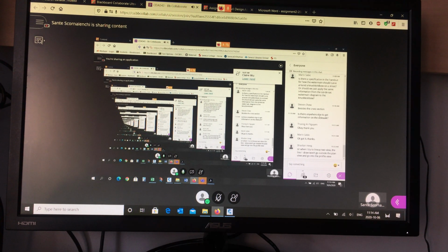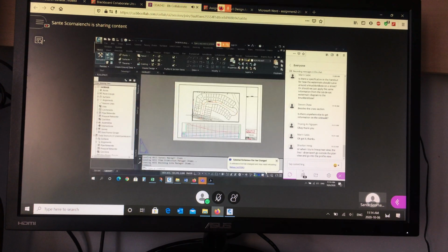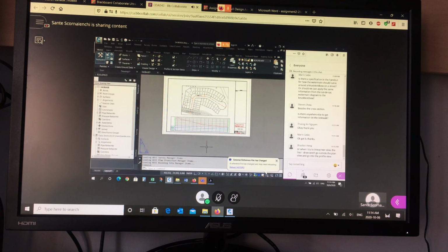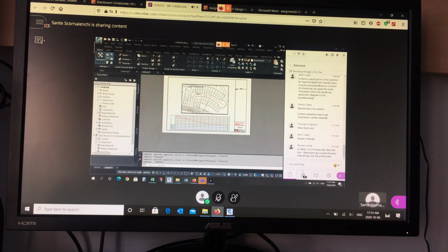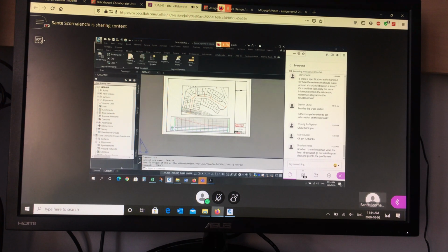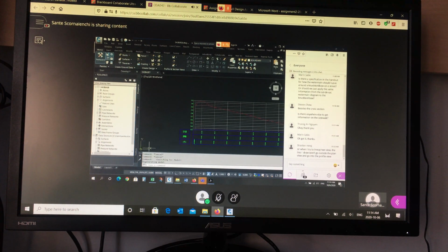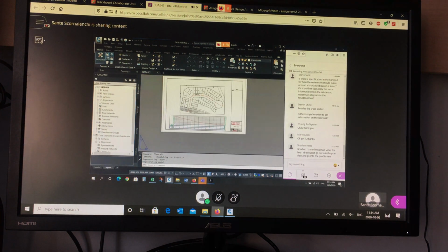So, Sheldon, I think you're probably not in paper space. So let me talk about that one more time. This is a lesson in paper space, model space. See this icon? It looks like a triangle. That means I'm in paper space. If I click inside the frame, then you'll see the stick figure that you see in model space. Let me go to model space. So see in model space, it looks like two lines, but in paper space, it looks like a triangle.